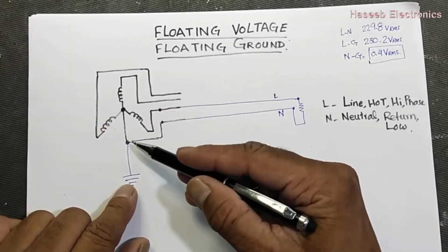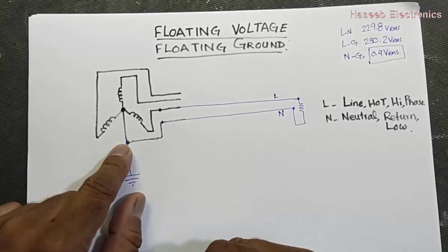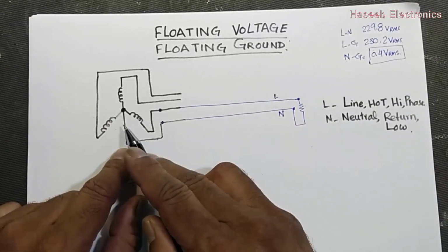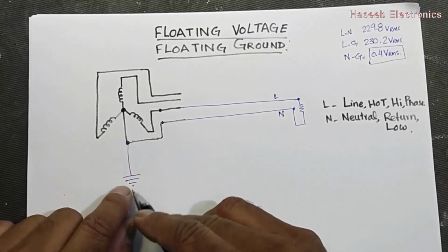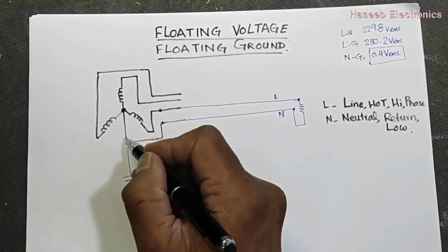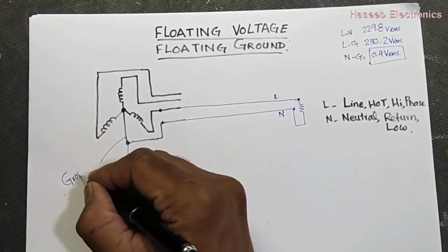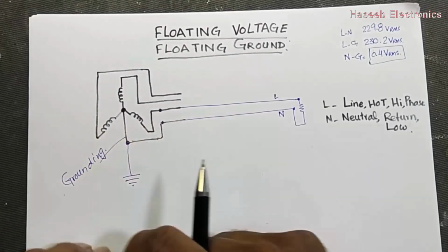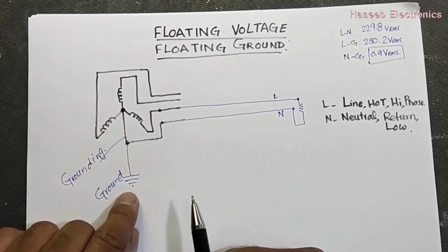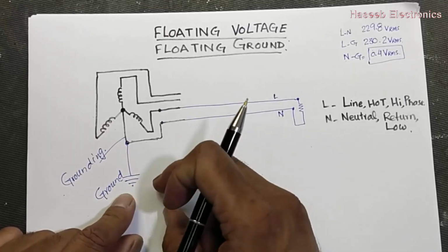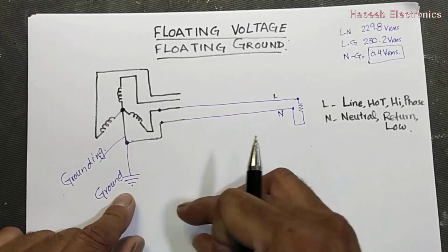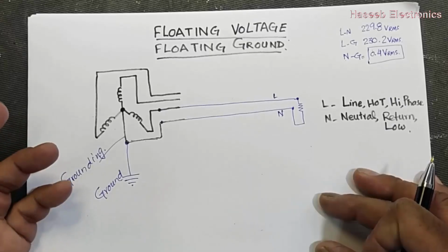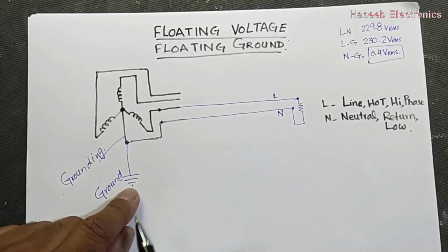It is for safety. Connecting the neutral line, the low side current carrying conductor, to ground is called grounding. It is defined as grounding, because earth is the biggest electron source in the planet. It will be a reference point.